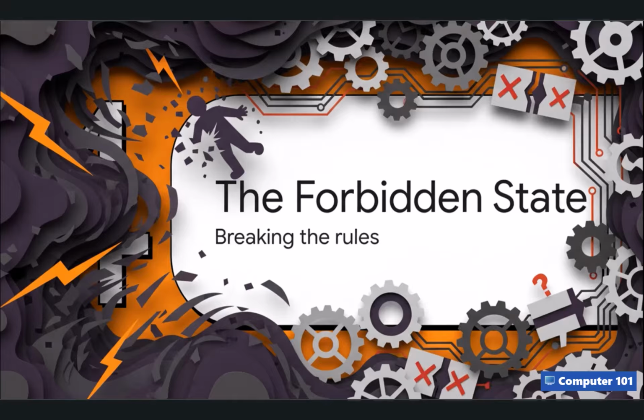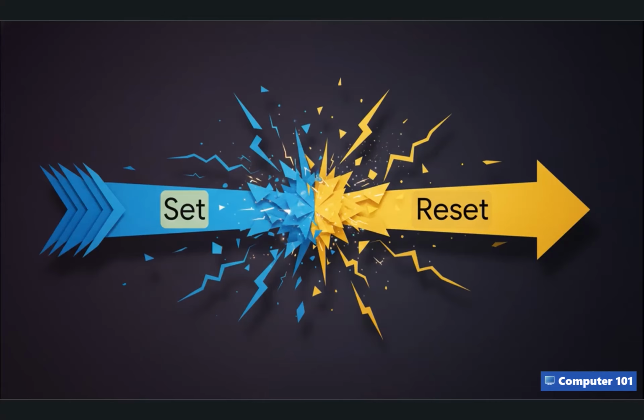Which brings us to Section 4, the forbidden invalid state. So, we have a working memory cell. It's brilliant. But there's a catch. A strictly critical rule of the little universe we just built is that Q and Qn must always be exact complements of each other. If one is 1, the other is absolutely 0. But what happens if we break the rules? What happens if we instruct the circuit to set and reset at the exact same time?